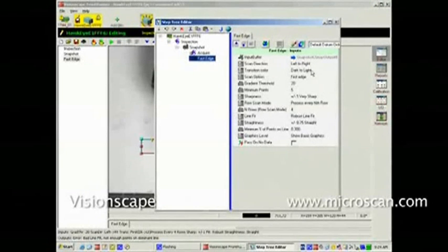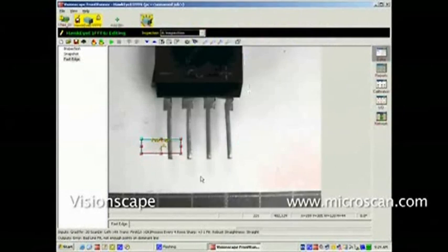Scan direction is correct, left to right. We'll make the adjustment to make it look for a light to dark transition. Put away that tool datum editor page for a moment and click on the edge, and yes, it has found what we desire. So bring back the editor.